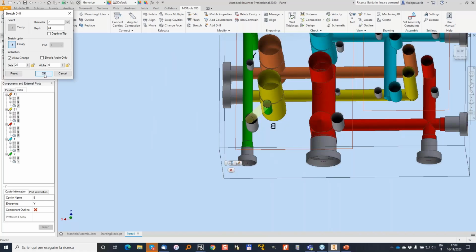Slightly less, 22 degrees. MDTools is warning because now the shape for the inclined drill will exceed the maximum shape allowed by the drill. The maximum value I can make is 6.49, so I will make it 6 millimeters. That's enough for the drain.